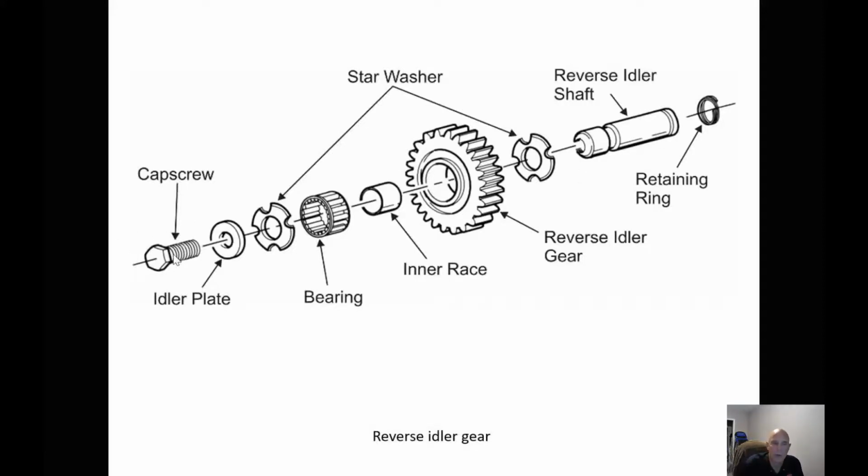Now there's a bolt that runs through the shaft, and you can put a slide hammer on the bolt to pop these pins out. When we're going to reassemble it, one of the things to pay attention to is the direction of the gear. In one direction it will spin freely, but if we put it in the other direction and tighten it up, it jams up against the case and it won't spin.